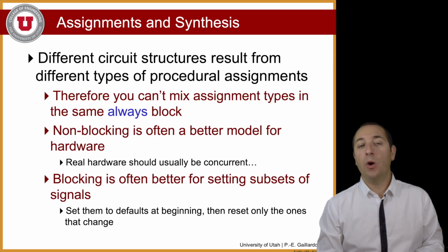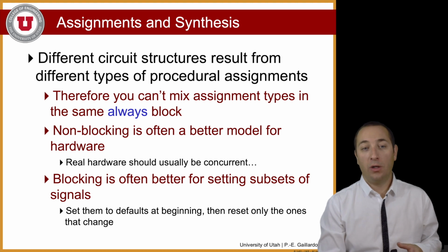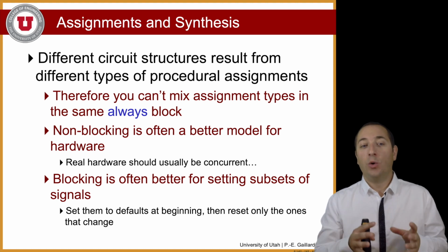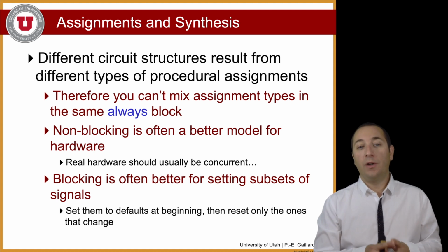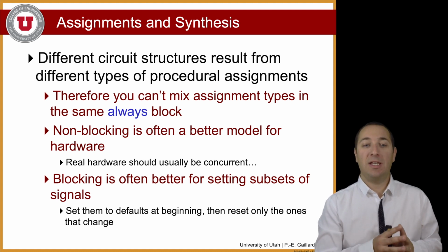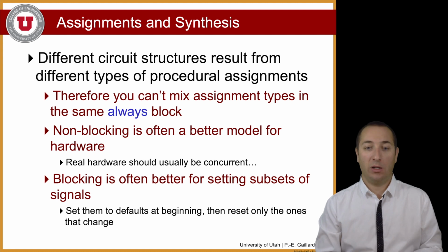Now, it is important to note that different circuit structures, as we just saw in the previous slide, will result from different types of procedural assignments. Therefore, you cannot mix assignment types in the same always block.